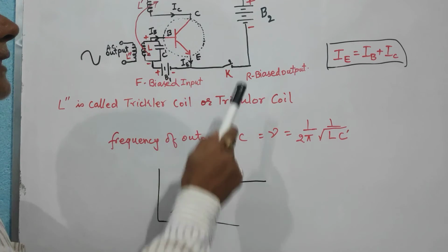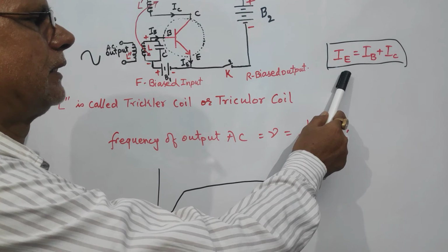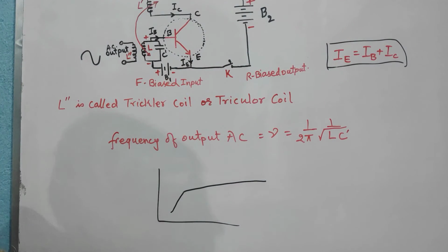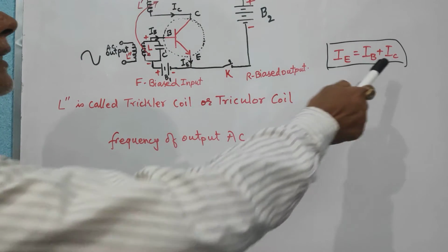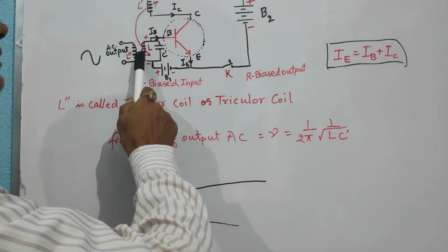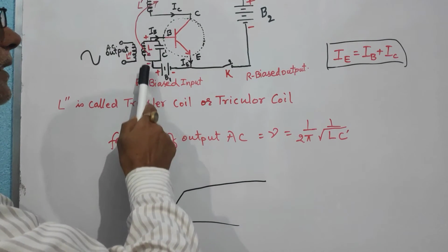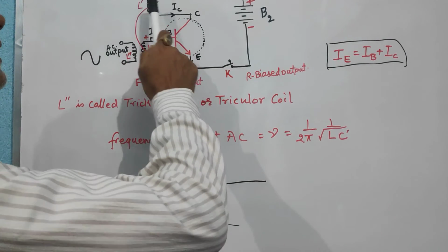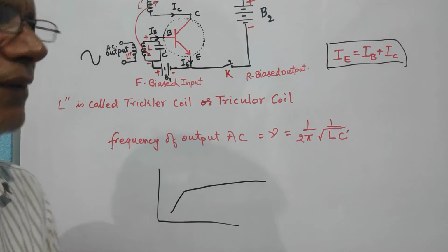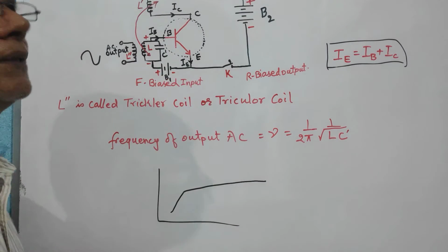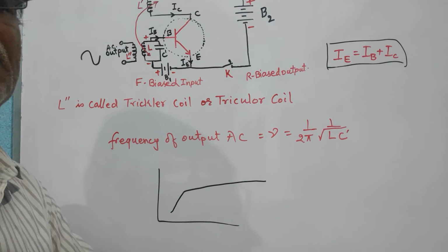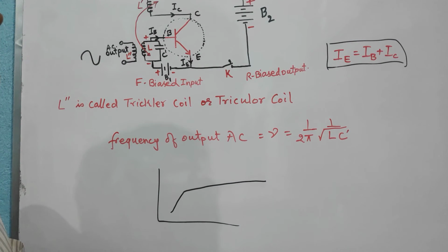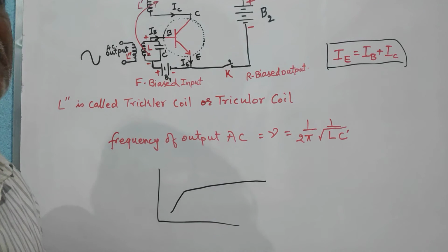and as a result it will oppose the forward bias, and the emitter current decreases, again further the collector current decreases, and this happens in a loop again and again. So each time the collector current decreases, the EMF produced across L is opposing the forward bias, and finally a stage will come when the collector current becomes zero, as if this circuit is again open. The output circuit virtually acts as if it is open, and once this happens, the whole cycle is completed,